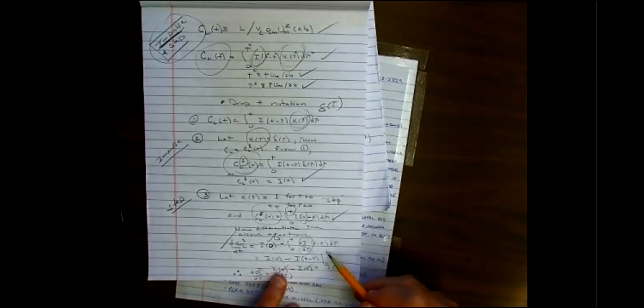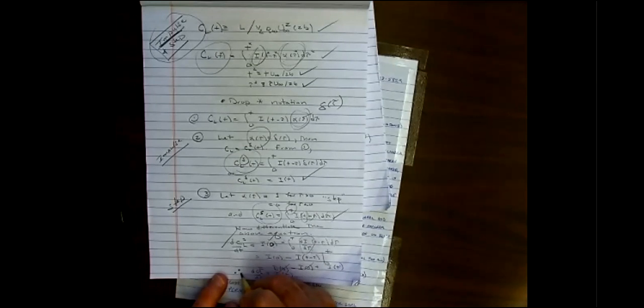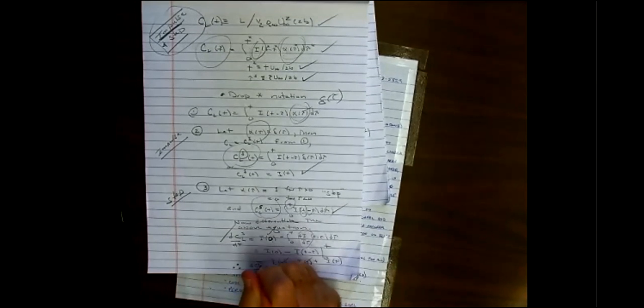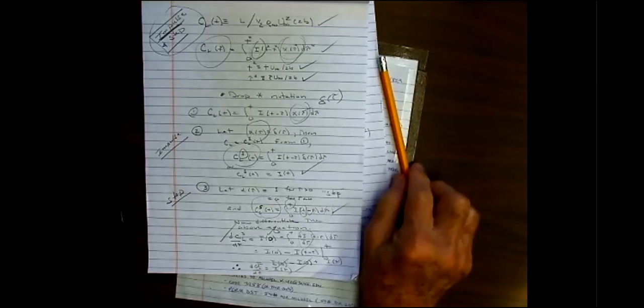It's just I of t minus tau evaluated between the limits 0 and t. And when you get that, the upper limit gives me I of 0, which cancels this one. And what I'm left with, through the lower limit, which also has a minus sign associated, is I of t. So what I've shown is that the derivative of the lift coefficient due to a step with respect to time is equal to this wonderful impulse function. So this is a better way to compute the impulse function using the step change.